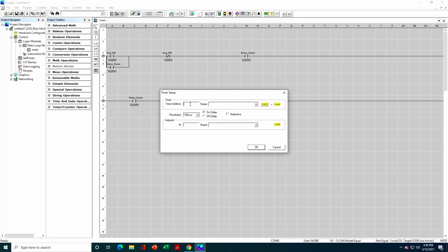So if I were to type in %R1, remember I don't have to type in the % sign. I'm selecting a general purpose register with my R type, and I happen to be picking number 1. It doesn't really matter which one I pick. And what's going to happen here is what's actually going to be assigned to the timer. R1 is the first 16 bits, and that's going to be my accumulator, which is timing or accumulating a time value.